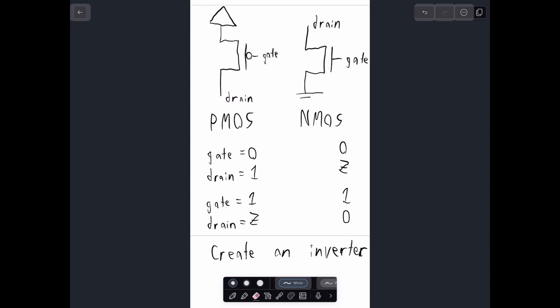So then we need the NMOS circuit to drive 0 for the case when we have 1 and 1. How can we drive 0 if we have 1 and 1? What if we put 2 NMOS in series to go to ground? Yeah, I really like that. So if we put NMOS and NMOS, hooked up to ground, so this is A and B, right?